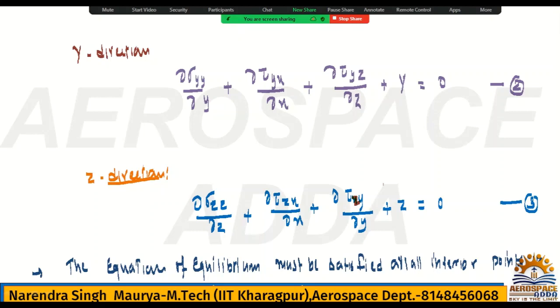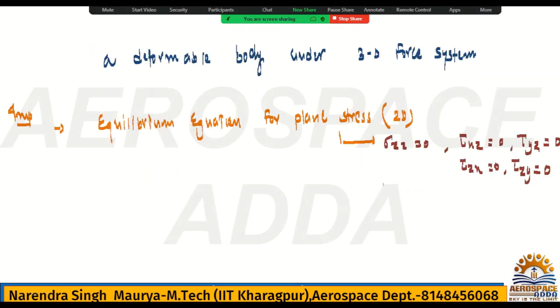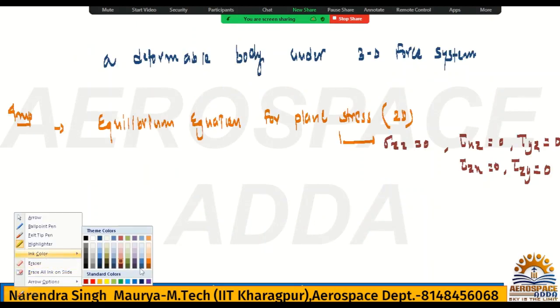So how many equilibrium equations will you get? Yes, tell me. Sir, capital X, Y, Z, these body forces will remain the same, no? No, if you are considering only a 2D system, then the body force in z direction will be 0. You are not considering that. Sir, for Y direction, will capital Y be 0? No, capital Y will not be 0. You are considering the XY plane, so X force and Y force will be there, but Z force will be 0. Understood? Yes, sir. So now how many equilibrium equations do you have? 2. You need to write. This is very important.